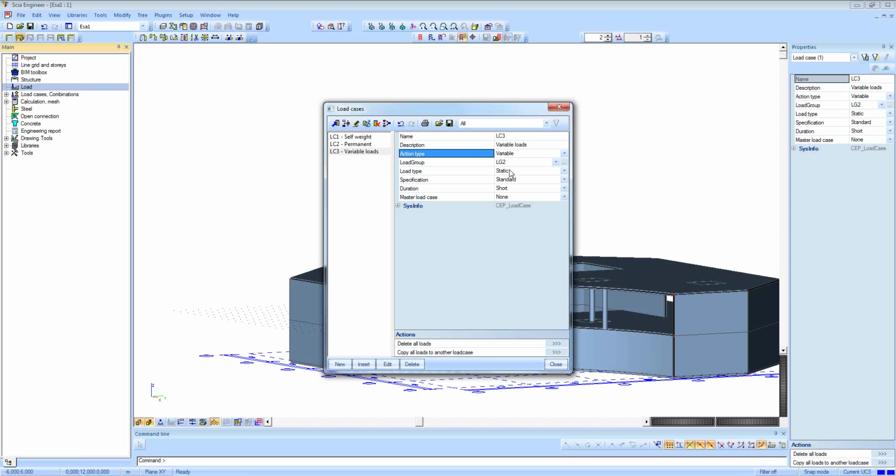So you have ground acceleration spectra, or ground accelerations, which you're going to apply to the structure. And those ground accelerations are going to create forces, and you can calculate them in Scia Engineer with dynamic load cases.